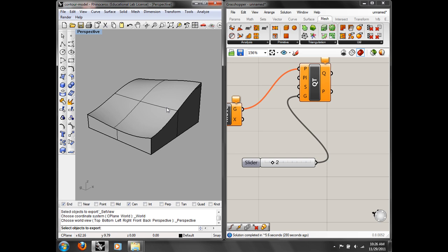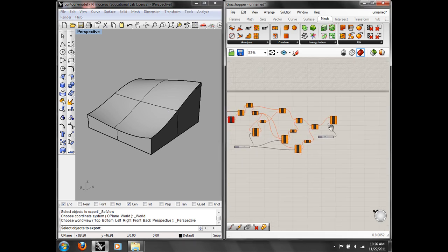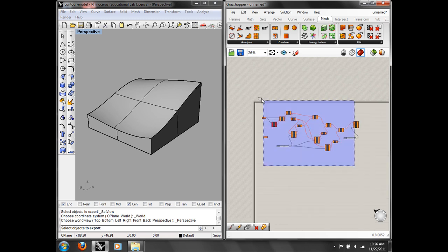I had this nice model that was already sculpted, but I wanted to send it to a laser cutter in nice sheets, and I don't want to have to make a bunch of sections in Rhino and then move them and then flatten them and then arrange them and then label them. It's a pain in the butt, right? You can do it parametrically, really easily, all using the stuff that we've talked about in this class. So this is a really good thing that anybody should be able to do at this point. Go ahead and kill this all.